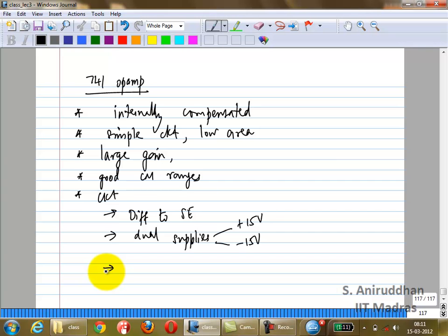In this particular case, the bipolar does take an input base current. You want to reduce it as much as possible. So you're going to try to increase the input resistance and reduce I_B, in other words. This is something special you have to do in this case.